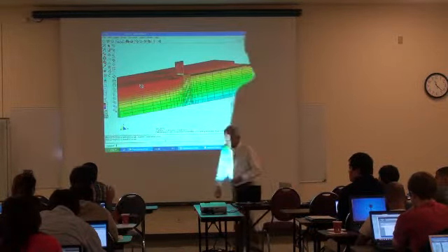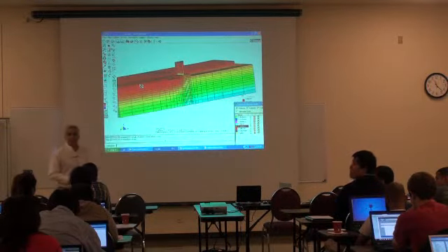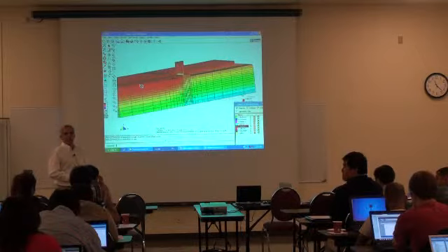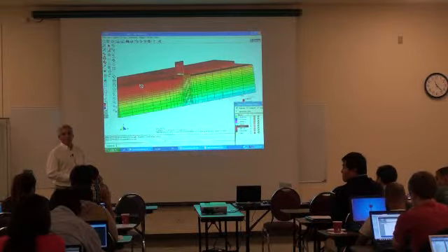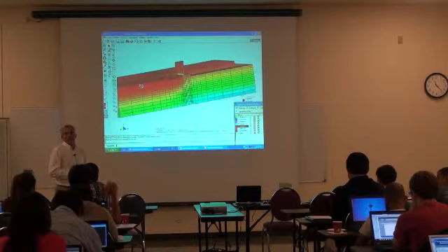I have a question on the ND material. As you showed, we use ND material pressure dependent for sand in drained condition, right? So what if we have sand but in undrained condition?